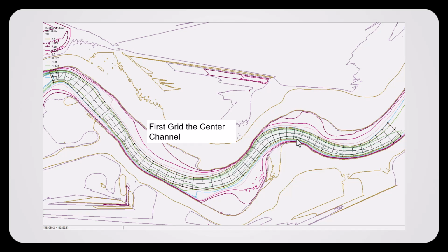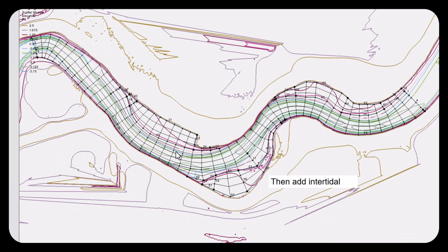So the way I usually handle this is to grid from the center out, starting with the deeper section that's clean. In this example, I put 4 elements in the deep part of the channel. Next, I grid up the slope to the always wet contour, which is about 0.45 meters. There's a little wiggle to go with that choice, but you can see that we've got a clean grid on the inside, and then we've captured that undulation in a simple way. And then we start capturing the intertidal area and extra storage area on the sides. So that's probably a good introduction to bathymetry.